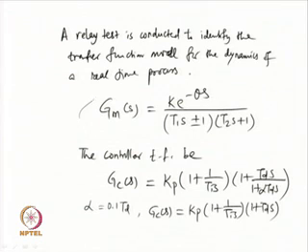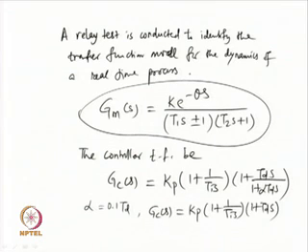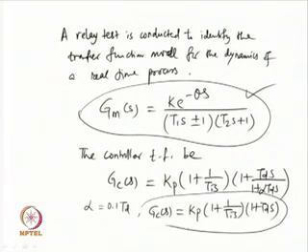So, assuming that we have with us the transfer function model of a plant given by this and a series form of PID controller of this form, we will proceed with our analysis. We will find explicit expressions for Kp, Ti and Td in terms of the model parameters of the plant dynamics, that is, in terms of K, theta, T1 and T2.